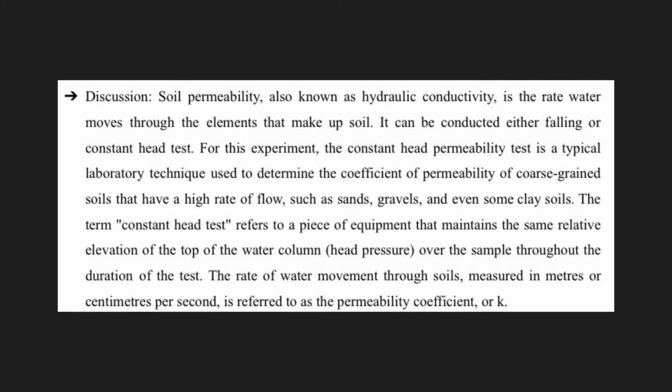The discussion of this experiment is soil permeability, also known as hydraulic conductivity, is the rate water moves through the elements that make up soils. It can be conducted either by falling head or constant head test. For this experiment, the constant head permeability test is a typical laboratory technique used to determine the coefficient of permeability of coarse grain soils that have a high rate of flow, such as sands and gravels.